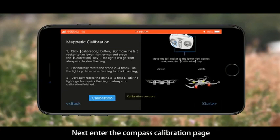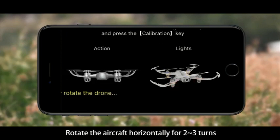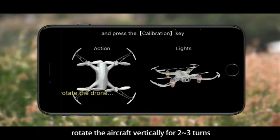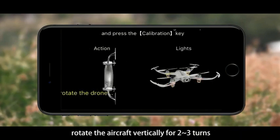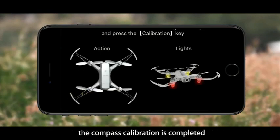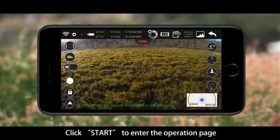Next, enter the compass calibration page. Click Calibrate. Rotate the aircraft horizontally for 2 to 3 turns. When the indicator light changes from slow flash to fast flash, rotate the aircraft vertically for 2 to 3 turns. When the indicator light changes from flashing to steady light, the compass calibration is completed. Click Start to enter the operation page.